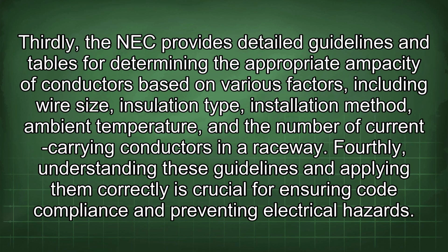Thirdly, the NEC provides detailed guidelines and tables for determining the appropriate ampacity of conductors based on various factors, including wire size, insulation type, installation method, ambient temperature, and the number of current-carrying conductors in a raceway. Fourthly, understanding these guidelines and applying them correctly is crucial for ensuring code compliance and preventing electrical hazards.